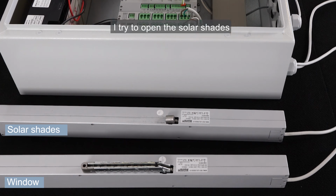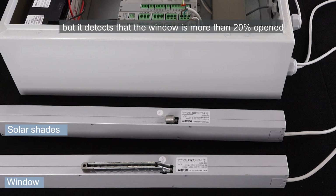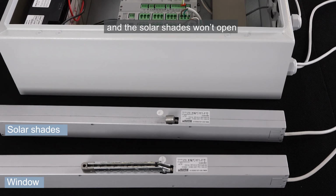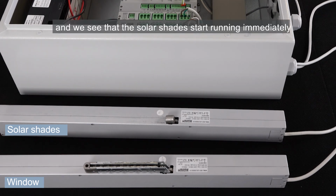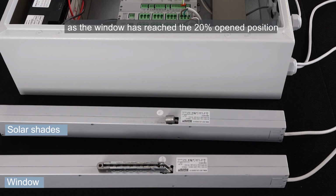I try to open the solar shades, but it detects that the window is more than 20% opened and the solar shades won't open. I'm closing the window, and we see that the solar shades start running immediately as the window has reached the 20% open position.